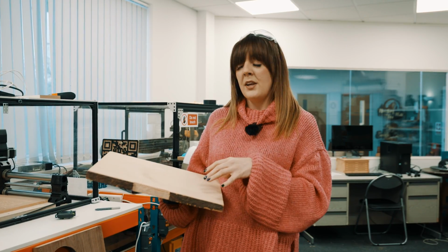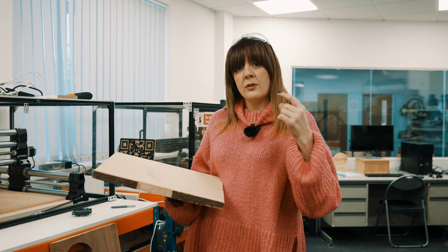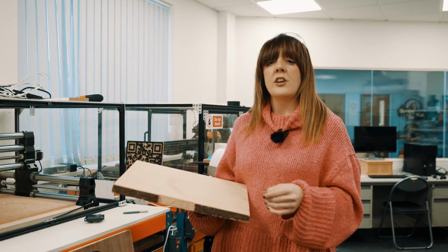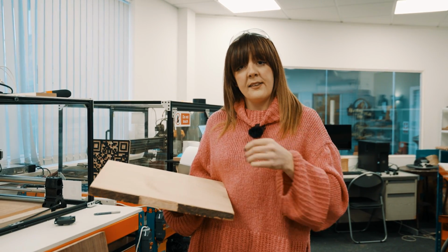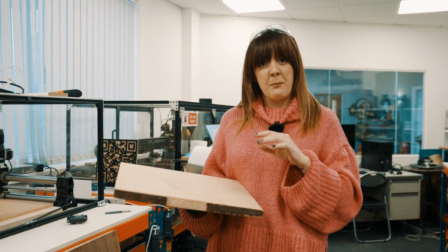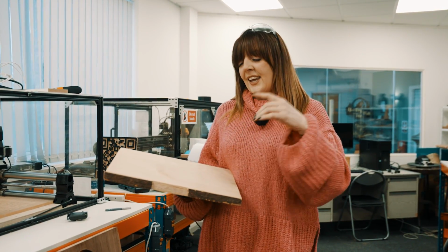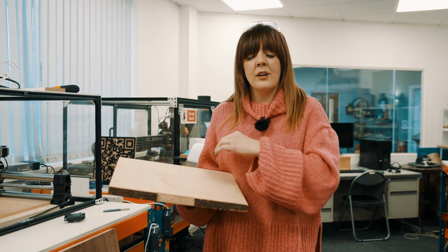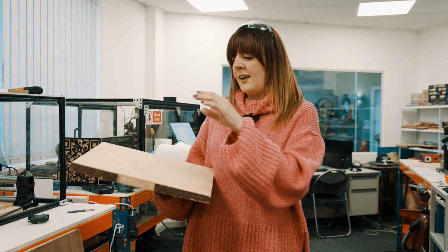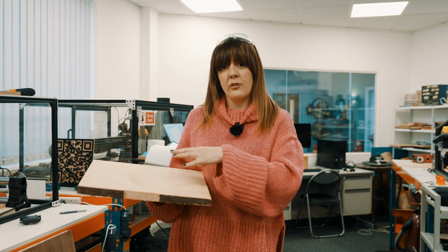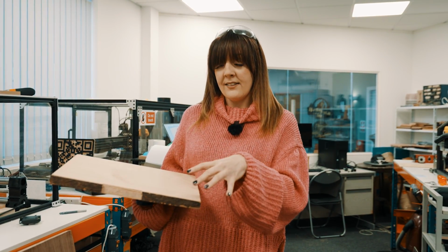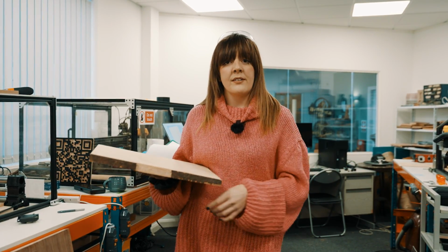So the first thing we're going to do is cut into the beech to create the base of our game. So we're going to have 3 tools. We're going to use a V-bit to create the crosshatch, the round bullnose bit to create the little divots, and then we'll test our marbles fit in there nicely. And then we're going to switch to that 1/4 inch where we're going to cut everything else out, and that will be that done. And we'll just check that everything fits in place. Take that off, and then we'll go on to the walnut to cut the ring out, and then we'll see how it all goes.